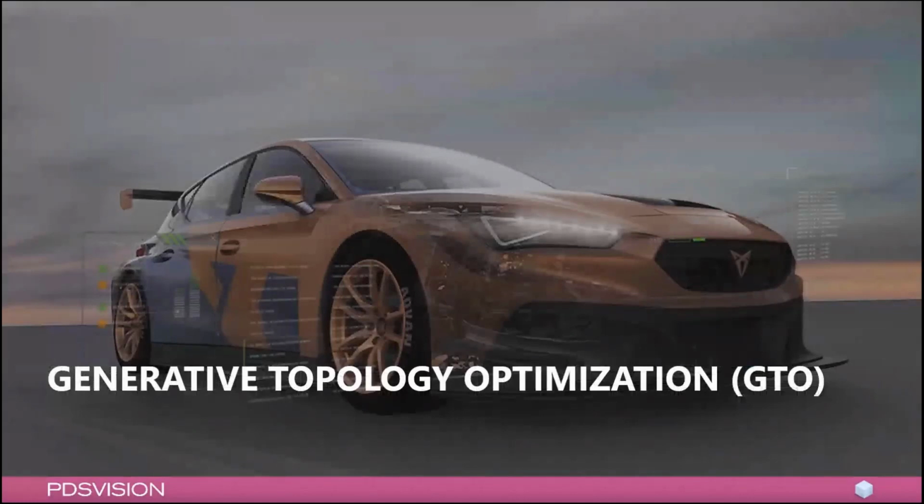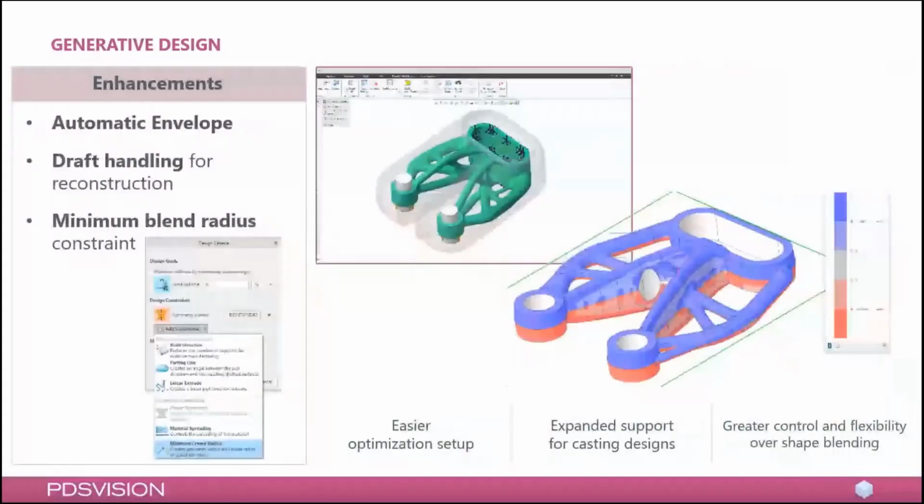Then another computation application is generative topology optimization, which was introduced in Creo 7. In there, what you do is basically define an area where you want to, for example, fix things. Then you also define areas where you can't go, and maybe some additional geometry for the loading. Then you load it and let the system find a solution that fulfills the design criteria.